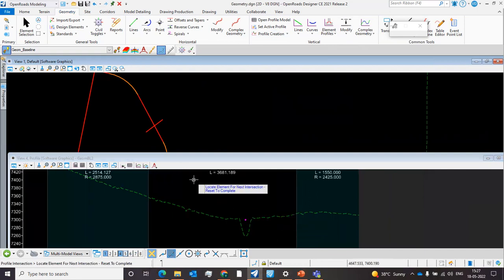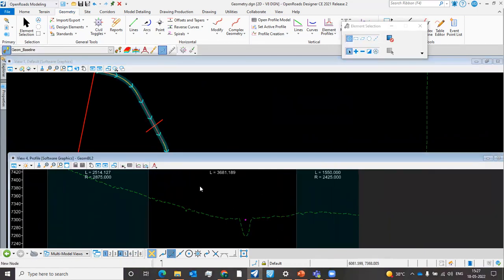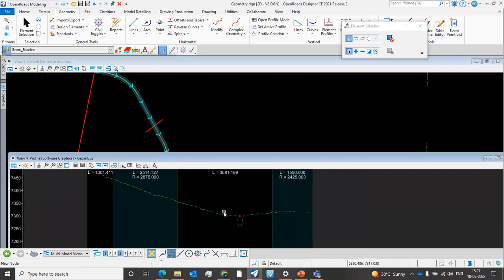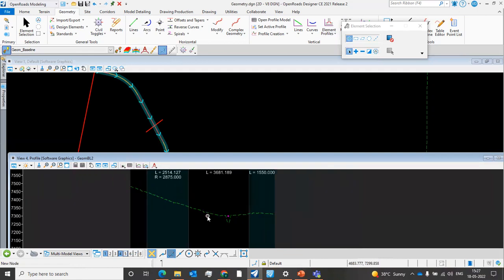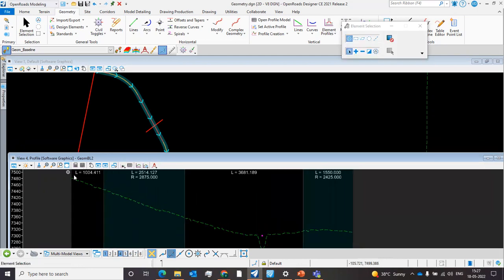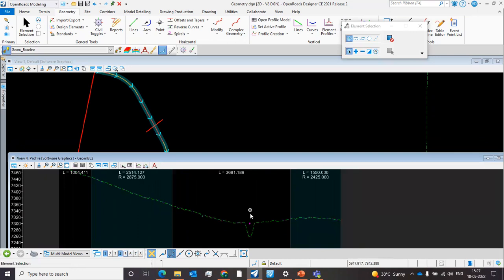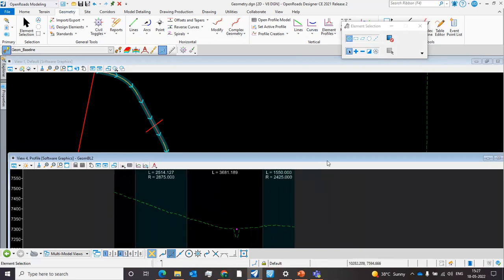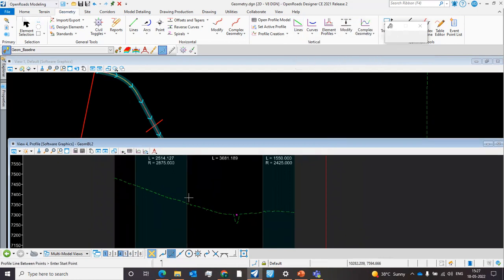And we are in profile view. As we go in profile view, we automatically get to know in which horizontal alignment's profile view we are currently present. So we need to create an alignment from here like this, and at this location it should maintain 25 or 20 meters, or whatever you need, a distance of 20-25 meters. And whenever the level of this alignment changes, the level of our main alignment also changes. So let's draw. I'll draw simply two lines using the horizontal tool.